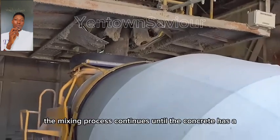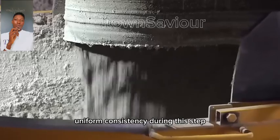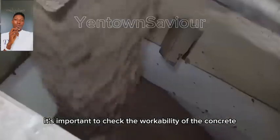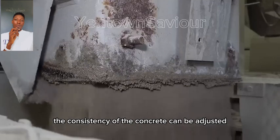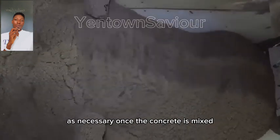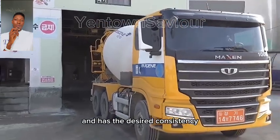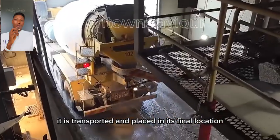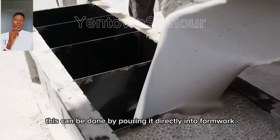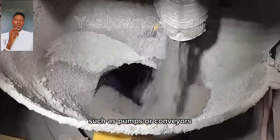The mixing process continues until the concrete has a uniform consistency. During this step, it's important to check the workability of the concrete. The consistency of the concrete can be adjusted by adding more water or dry ingredients as necessary. Once the concrete is mixed and has the desired consistency, it is transported and placed in its final location. This can be done by pouring it directly into formwork, molds, or by using specialized equipment such as pumps or conveyors.